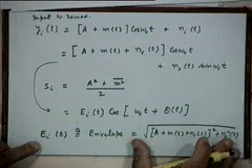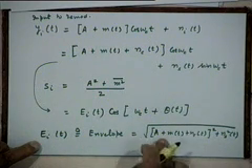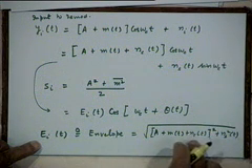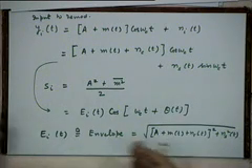So, I am not even going to write it down, because finally the envelope detector will produce an output which is proportional to the envelope. This is the main thing of interest to us, and it contains, as you can see, the signal part as well as some noise part, but there is a non-linear dependence now, and that is what makes the situation in general a little more difficult. To simplify the situation, one makes some assumptions, and the usual assumption that we make to do the initial analysis is the small noise assumption. So, let us make a small noise assumption.